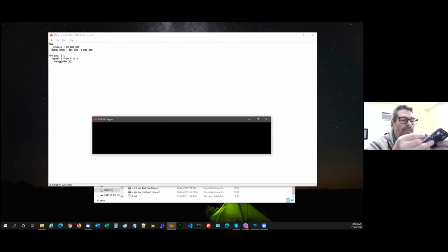But there is some configuration that goes on with these things. I remember when we built these FT231XS, we must have configured these chips differently, but it's not something you can't reconfigure on your end too. I just don't know what the trick is. On the eval board, we set it up so that some of the pins operate the power sensing and power switching, and then the LEDs which indicate TX and RX.